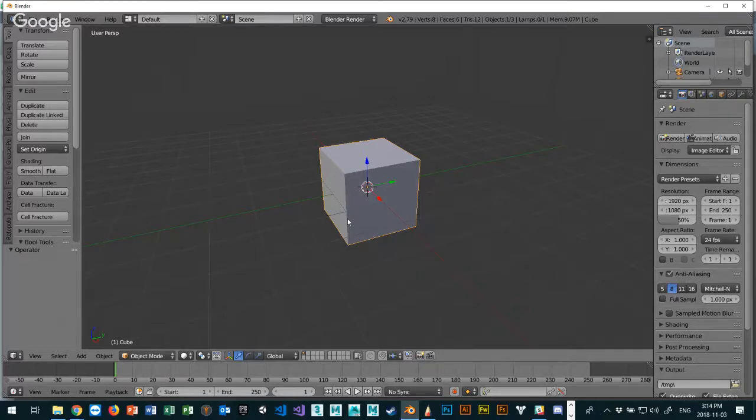In Unity, what is the orientation in Unity? Do you guys know? Y up, right? This is different. So when we produce something in Blender, we're using Z up, whereas in Unity, it's Y up. In Unreal, it's Z up. In Maya, it's Y up. Every tool is going to have a different orientation. Or maybe it's not every tool, but some tools have different orientations.